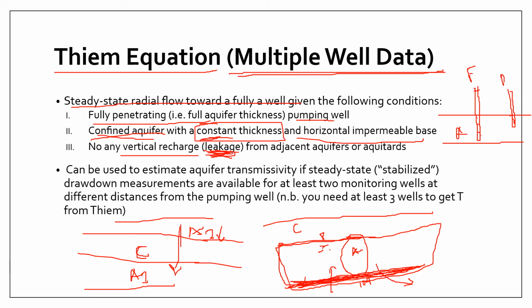It means that your Aquifer 1 is actually getting water from other areas, and that changes the effective hydraulic head of your aquifer, because it is technically connected to other water table levels. So that changes everything in your calculations.